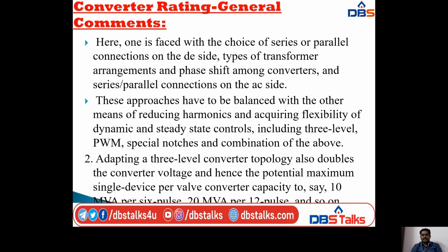The second option is adopting a 3-level converter topology. It doubles the converter voltage and hence the potential maximum single device per valve converter capacity to, say, 10 MVA per 6-pulse, 20 MVA per 12-pulse and so on. Like this, the capacity of the converter is increasing.